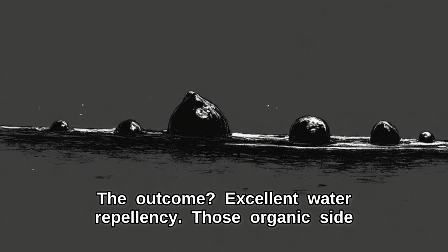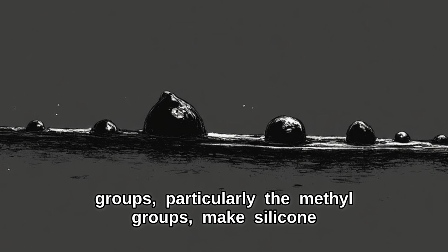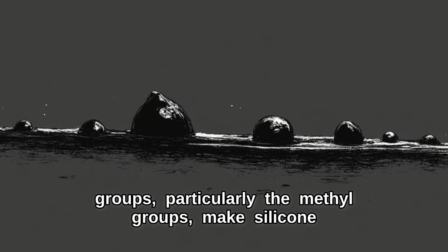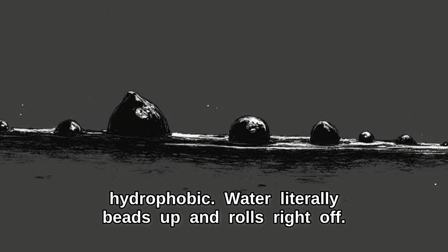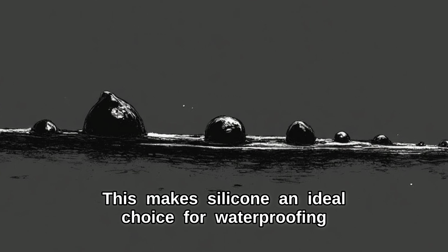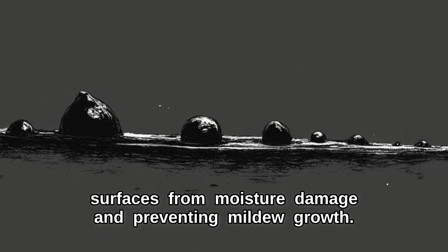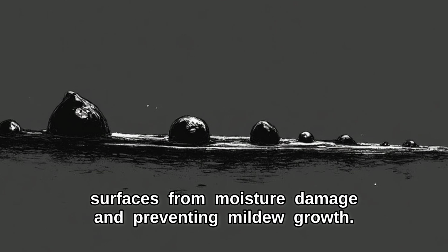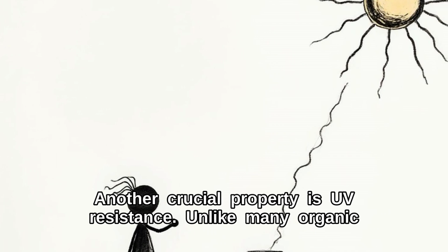The outcome? Excellent water repellency. Those organic side groups, particularly the methyl groups, make silicone hydrophobic. Water literally beads up and rolls right off. This makes silicone an ideal choice for waterproofing sealants, coatings, and even textile treatments, protecting surfaces from moisture damage and preventing mildew growth. Another crucial property is UV resistance.